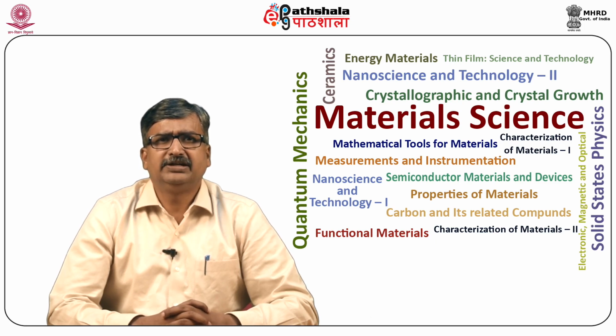In many oil field applications, wettability is treated as a binary switch. The rock is either water wet or oil wet. This extreme simplification masks the complexity of wetting physics in reservoir rock. In a homogeneous porous material saturated with oil and water, strongly water wetting describes one end member of a continuum in which the surface strongly prefers contact with water.